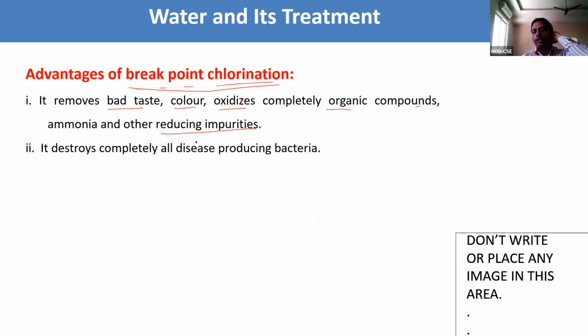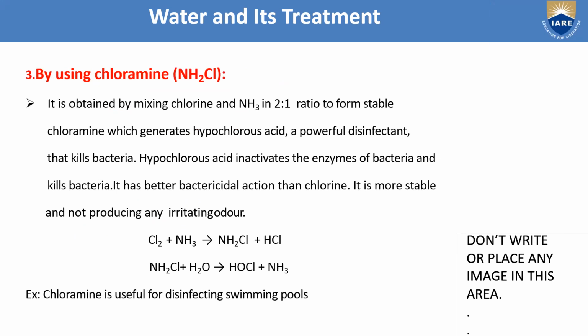What is the advantage of this break point of chlorination? It removes the bad taste and color of the water, oxidizes completely organic compounds, ammonia and other reducing impurities, and it completely destroys all disease producing bacteria present in the water. Nothing but the pathogenic bacteria that is present in the water.